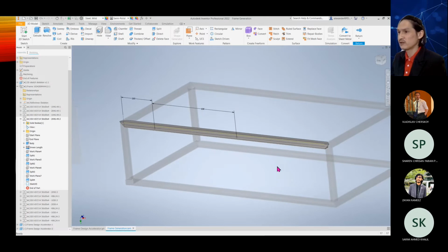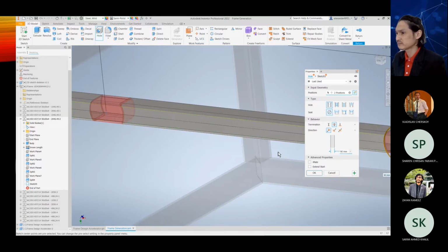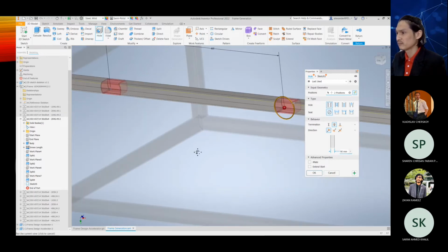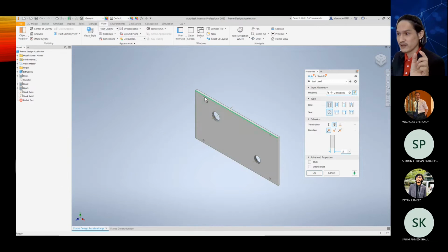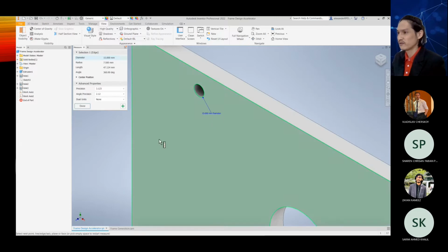So now I finish the sketch on it, just like normal part modeling. So I create the hole. Okay, over there. So it's too huge, 90. Okay, so now I just want to have 15, because just now we know that it's 15. If you're not very sure, you can go and measure again. But I think it's 15. So 15 diameter.